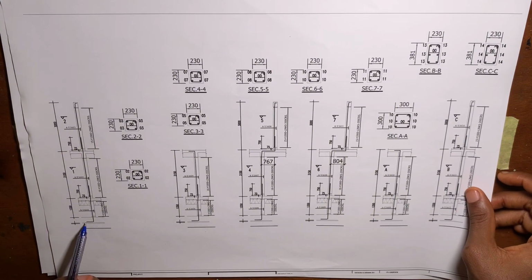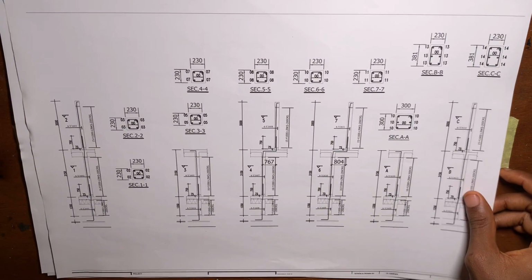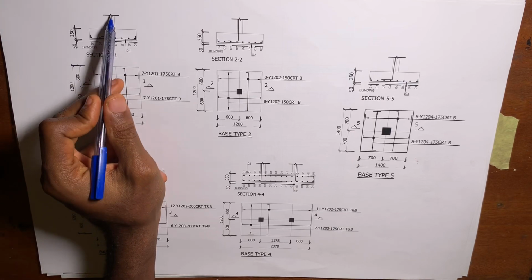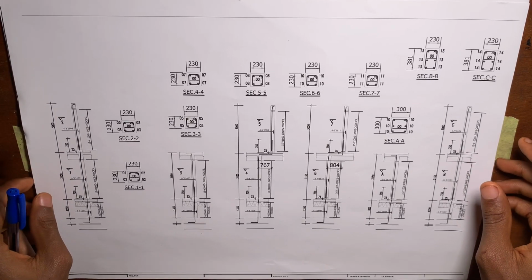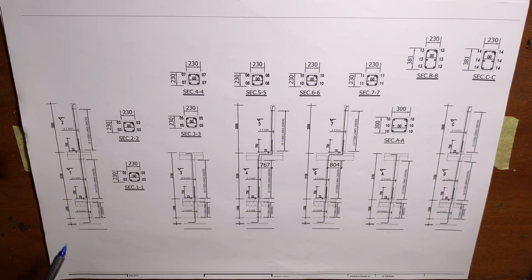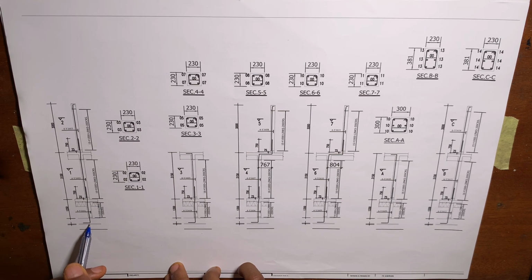Now please take a look at this. You see this thick line, this is reinforcement. You can see that it is the same thing we have in the section for our column base details, right? So I'm going to be explaining it better with this drawing. So now if you look at this, the starter column is bent in such a way that it will be attached to the column base. So now let's just say that this is, let's say, 300 mm. I'm making an assumption. So let's just assume that from here to here is 300 mm.